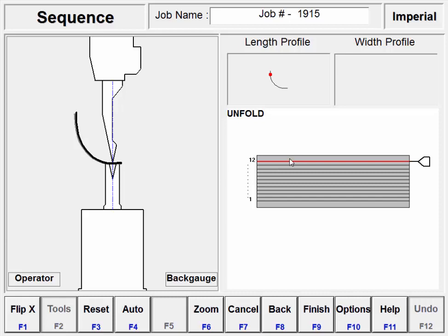If I don't have this extra material, and I only made my program to indicate it's a 2-inch 90-degree pair of lines to put my radius on, it'll try to put a bend on this last point, which it can't possibly do. There's no material to span across. So that's why we add this extra material.